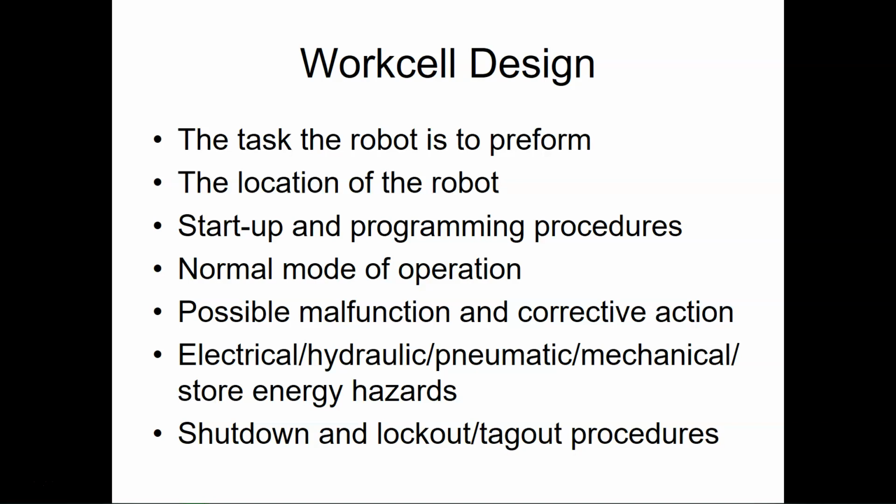Simply because you don't want to get pinched by anything hydraulic. Hydraulics are quite strong. Then you also have mechanical stored energy hazards, so something that might have a spring or something like that. And you need to make sure everybody's aware of shutdown and lockout tagout procedures.